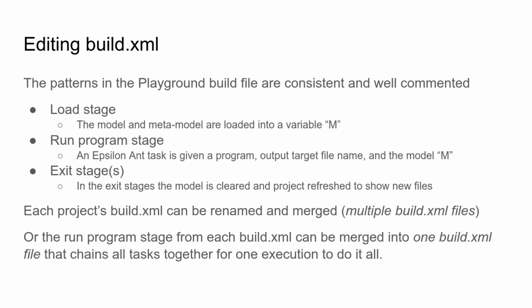Alternatively, instead of compiling all of the tasks into a single build XML, you could carefully rename each build.xml file and have each stage as a separate executable for an Ant runner. However, the fact that a validation stage can fail and block the run of a generation means it may be more advantageous in some cases to combine certain programs together such that if any program fails, the process of building your model into a product is stopped at the failing stage.